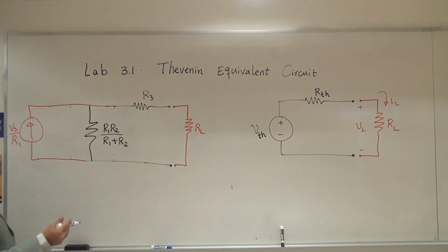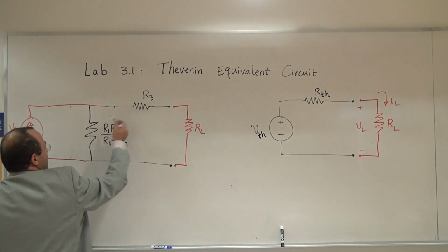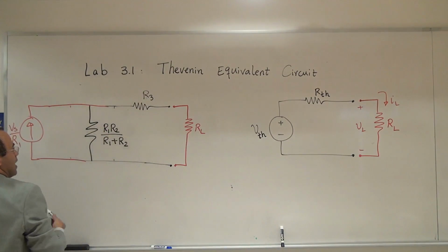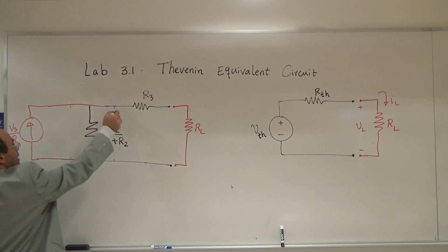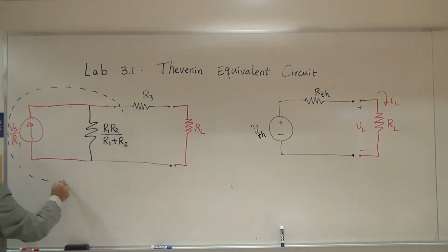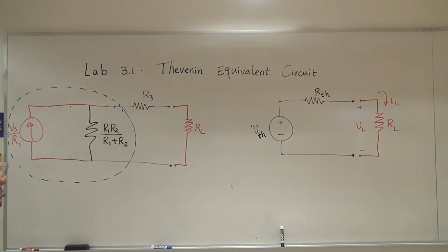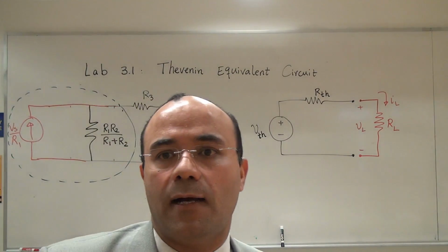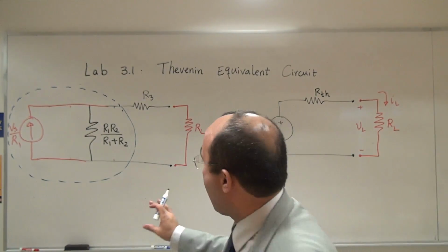Now, what do I have and what do I want to achieve? I want to have this structure. I can't see this in series. I can't see them in parallel. And that's a roadblock for my simplification process. But I do see something in front of me that's going to help me to reform and have it better. If I have this in mind, a current source in parallel with a resistor, and if I do one more source transformation, that source transformation is going to help me to change that to a voltage source and a resistor.